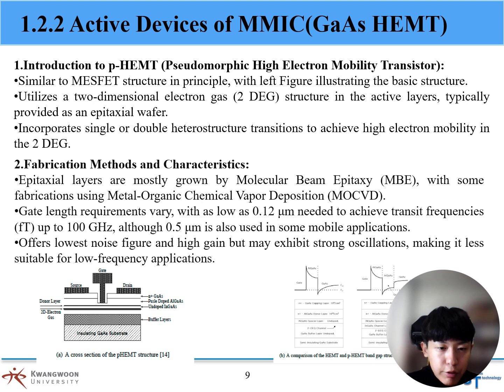Its gate length requirements vary, with as low as 0.12 μm needed to achieve transmit frequencies up to 100 GHz, although 0.5 μm is also used in some mobile applications. It offers the lowest noise figure and high gain, but may exhibit strong oscillations, making it less suitable for low-frequency applications.